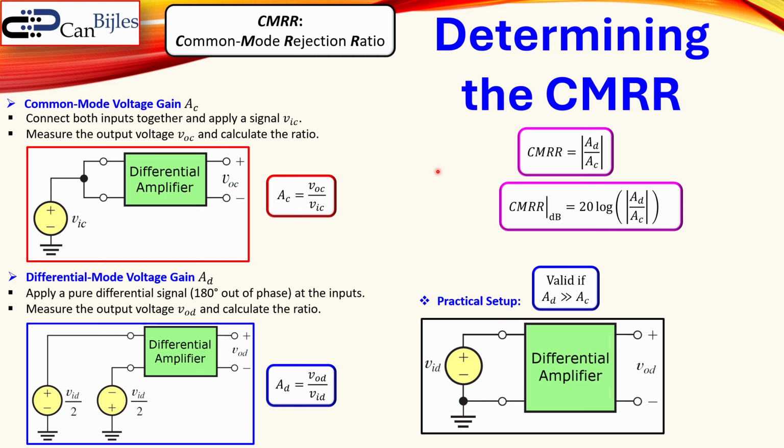Alright, that was our video about differential mode amplifiers in a conceptual view. We have discussed the input sources and looked at the common mode and the differential mode operation. And from there we also looked at the very important specification, common mode rejection ratio. And we also showed you a couple of examples and the simulation in SPICE to prove that the ripple is indeed eliminated using this differential mode topology in our amplifiers.